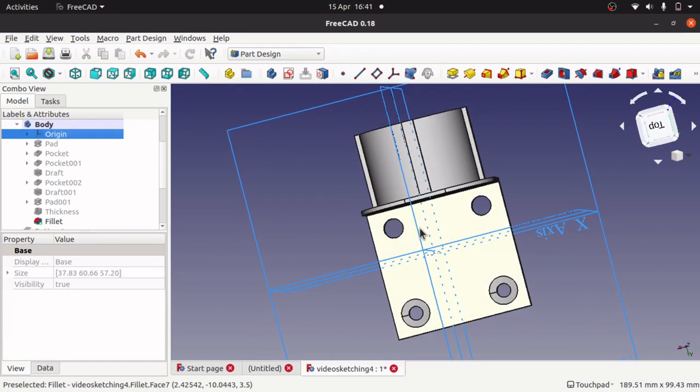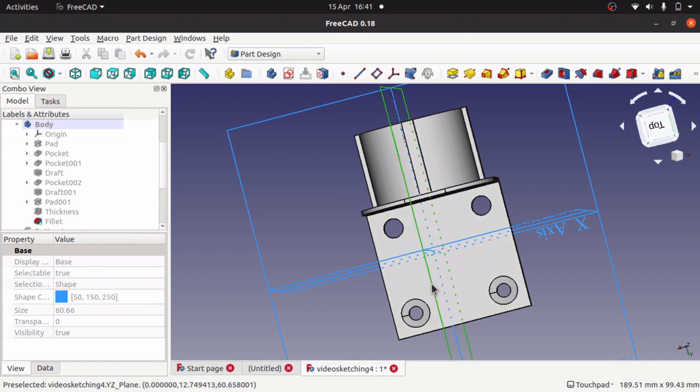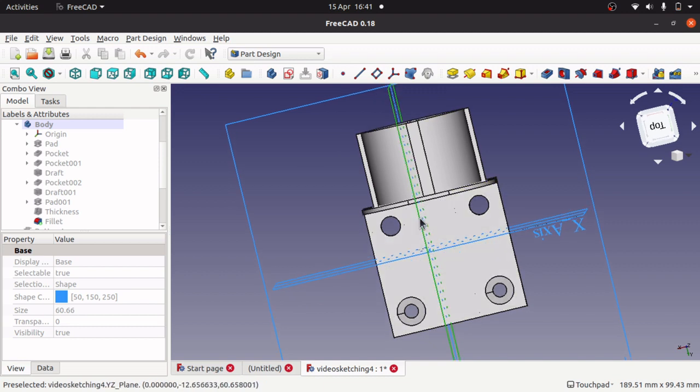and you can see that the origin here, this axis here, this plane, is not centered, and I really want that centered in the middle because I want to mirror across there. If I tried to mirror across there now with a sketch on here, what would happen is that if I place a sketch here and I wanted it to mirror to exactly the same place over here, then the origin isn't in the center, so it will mirror across and dump it around about the same width apart, but in the place that I don't want it. This has to be centered.